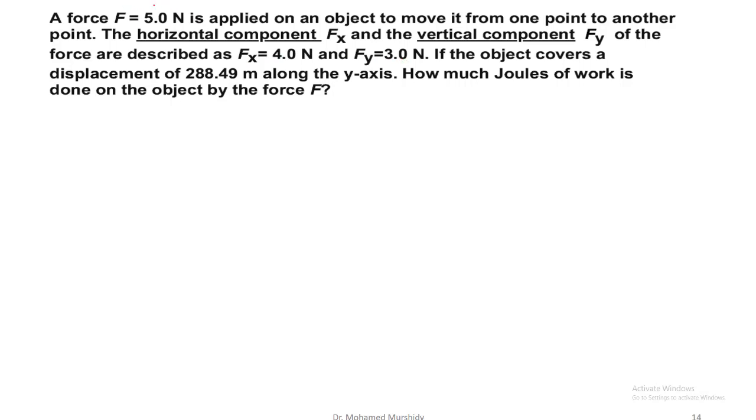So it looks like this force is not in the X or in the Y. It is something in between, like that. For example, here we have F, which is 5 Newton, and it has been resolved into two components, Fx 4 Newtons and Fy 3 Newtons.